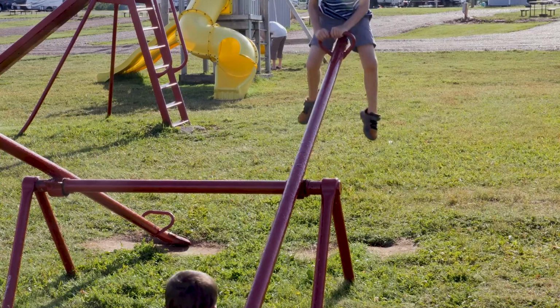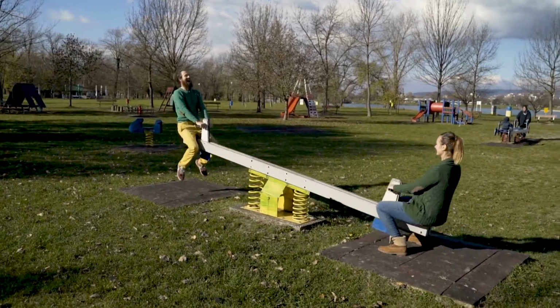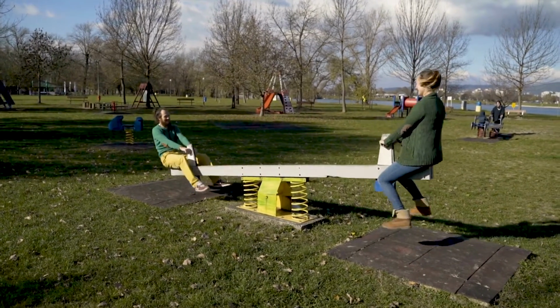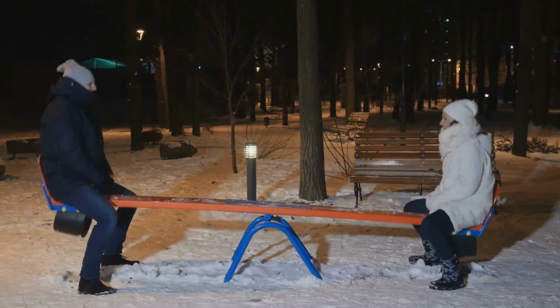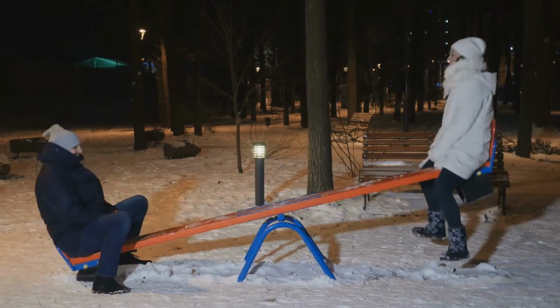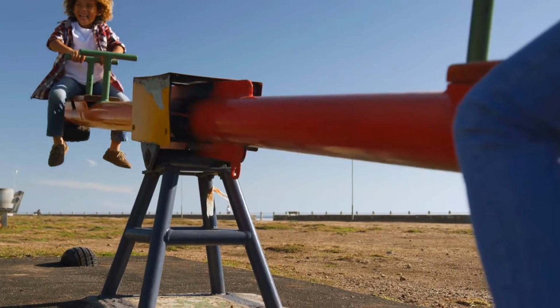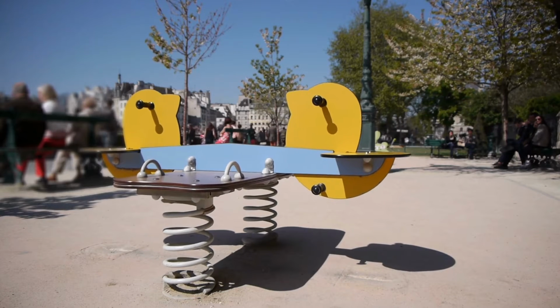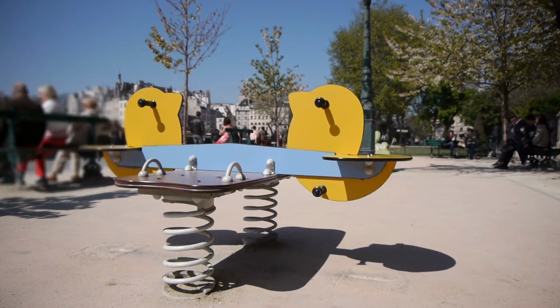When it comes to understanding the dynamics of operating a forklift, you can start by imagining a simple seesaw on a playground. It's a familiar and effective way to introduce the essential terms and concepts related to stability. First, the fulcrum is the pivot point around which the seesaw balances. It's the point that supports the entire system, allowing it to tilt back and forth. The center of gravity is the average location of all the weight in the system. For example, with no one on the seesaw, the center of gravity remains perfectly balanced at the fulcrum.